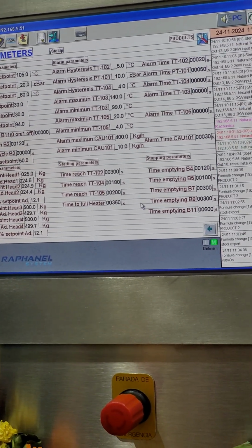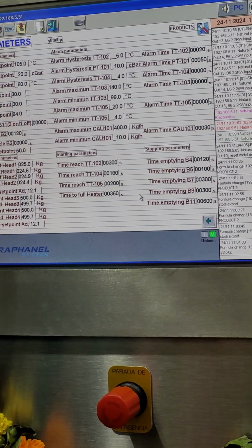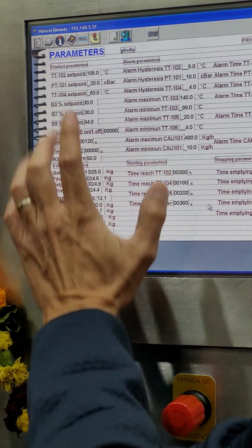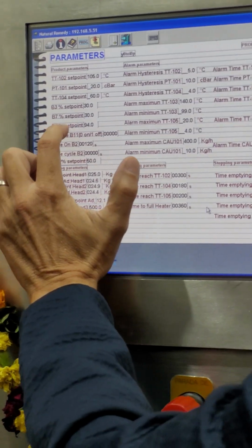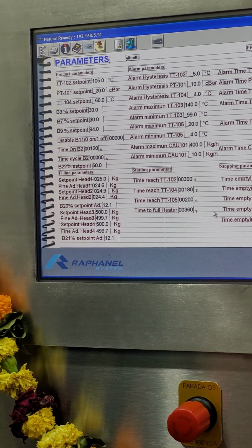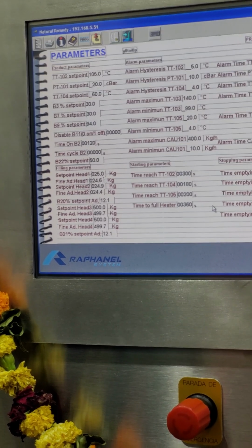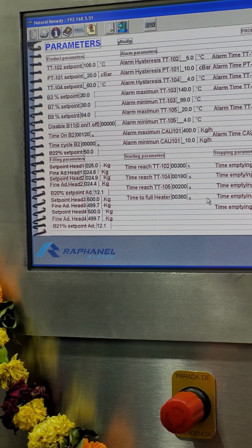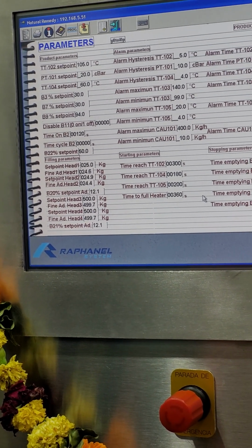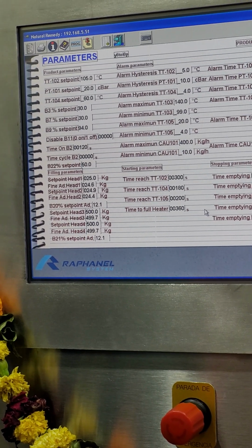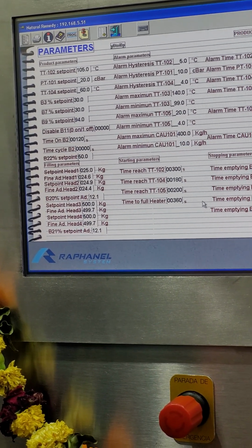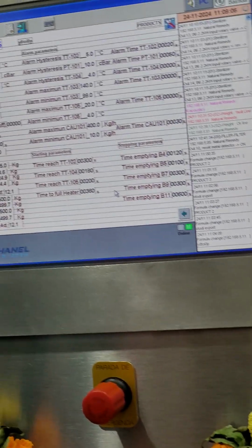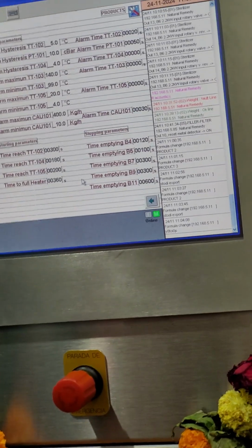I understood. This temperature, if I want to set 130, can I do it? Step by step. Usually you don't have to move the speed fast. Adjust to as low as possible, because fast means a lot of vibration and fatigue of materials. Vibration is not good. It's only to move the material. Material move is enough. You don't need to go faster because with less time here, you don't dry, you don't cool.